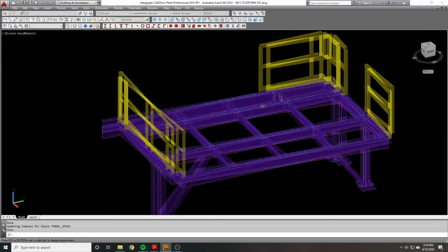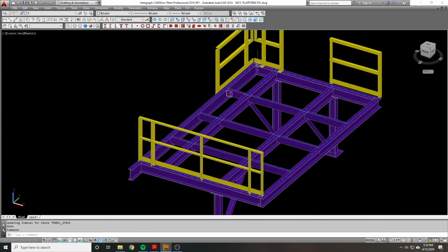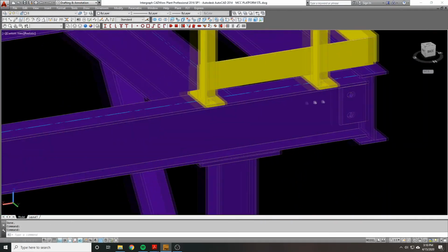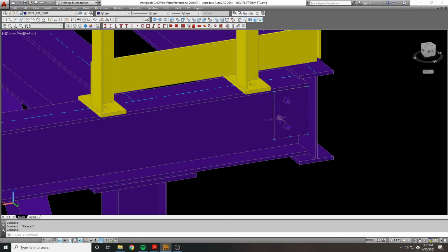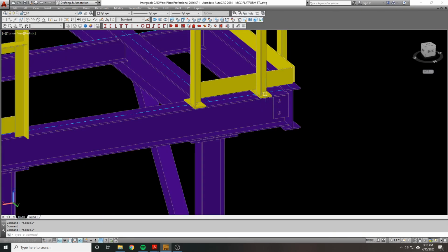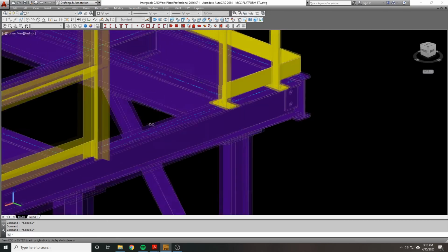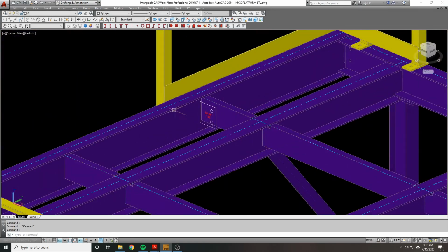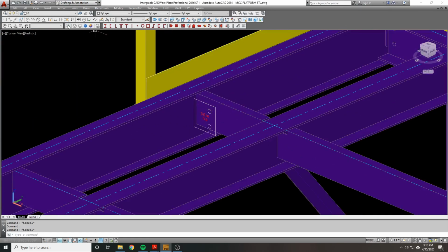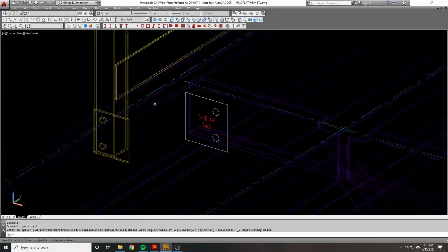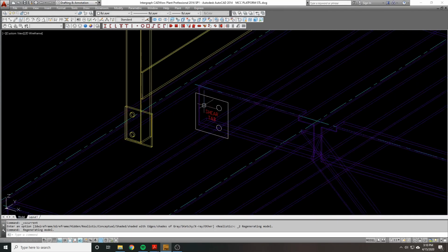of this dynamic block. So essentially what I want to do is make these connection plates where the ends of the beams meet. But right now for me to make this, I have to manually draw it out. And it's time consuming, and a lot of these plates are very similar in design. I can use them over and over again with just some minor modification. So what I wanted to do is make a template that I can use in multiple scenarios, which I've done here. So this plate is called a shear tab, and it's what connects some beams together.